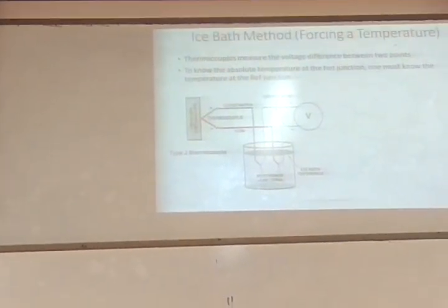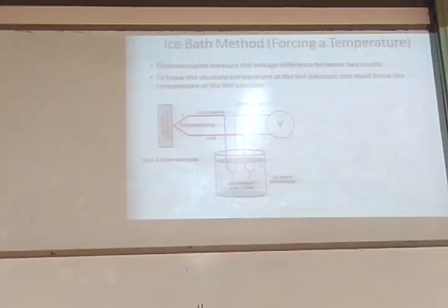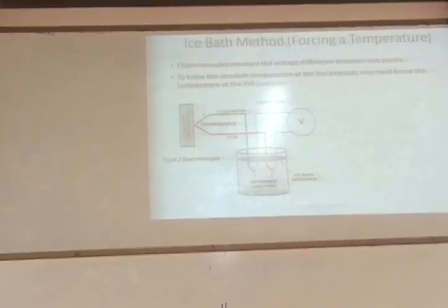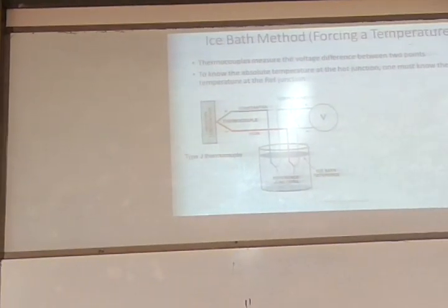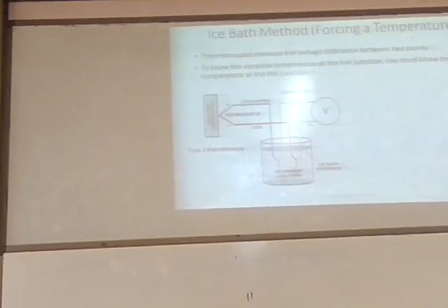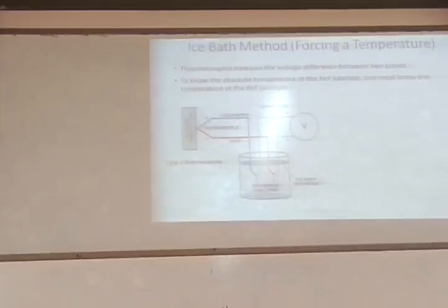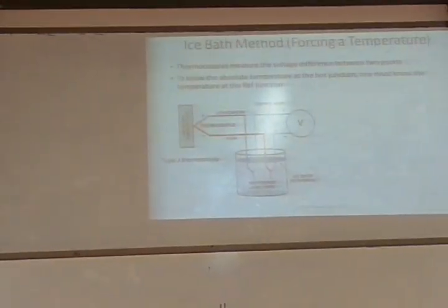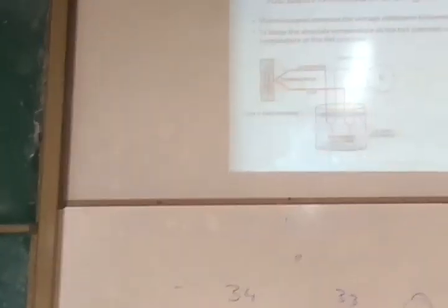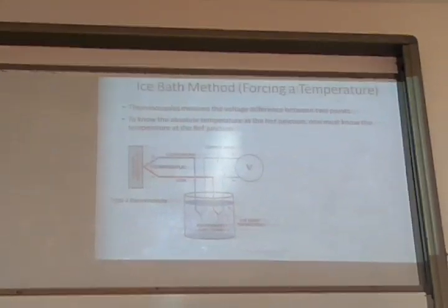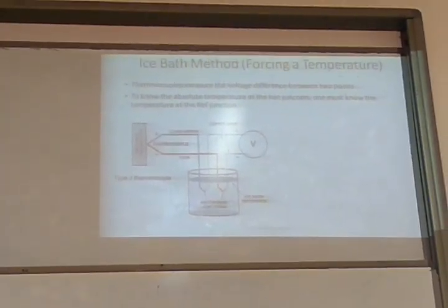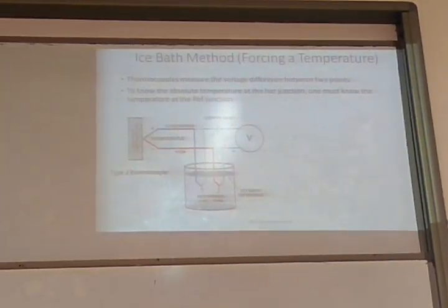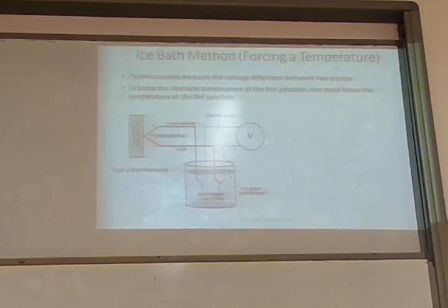Even though, see, to produce thermo EMF there are two conditions. One, the materials must be dissimilar. Two, the temperature should be different. You form two junctions. With respect to one junction, the other junction should be at a different temperature. If this is established, however small, there will be thermoelectric EMF. This is the principle. But if you are not able to maintain dissimilar material, or if you are not able to maintain different temperatures, thermoelectric EMF will not be there. Why do we need to have different?